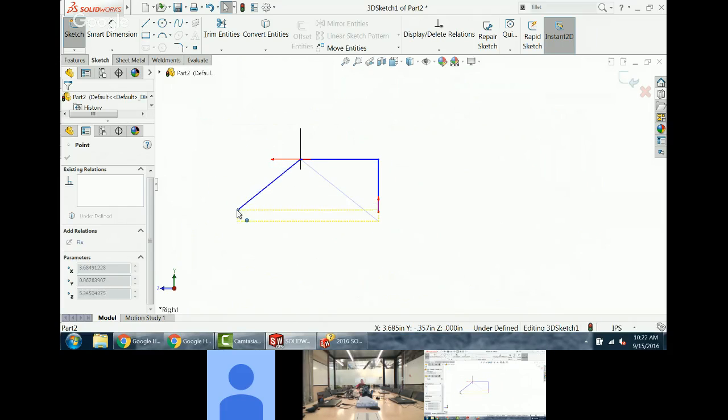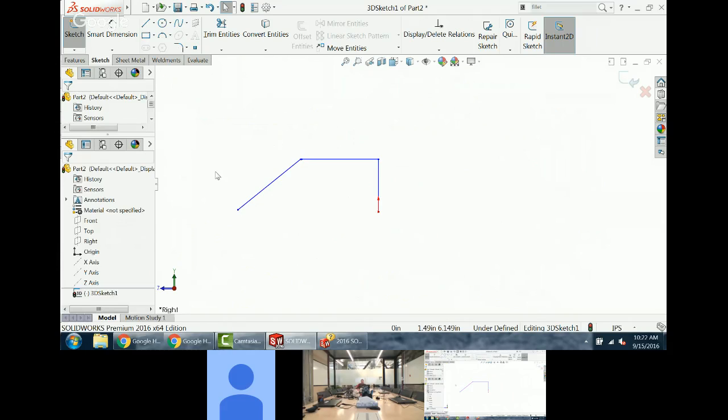So oftentimes when I'm trying to get things located properly inside of a 3D sketch, it's good to use the views and make sure you're only going in two directions at once, just so you don't get discombobulated. So does that mean it has some proportionality rules? It basically moves a point in the plane normal to your viewing vector. Exactly. It's moving in plane to how you're viewing it. It's not going to go back and forth on you.